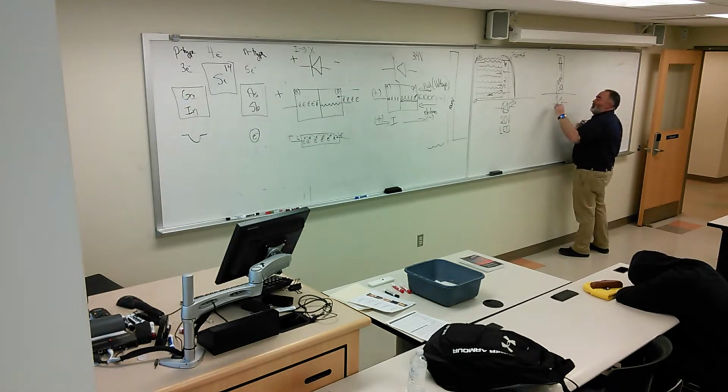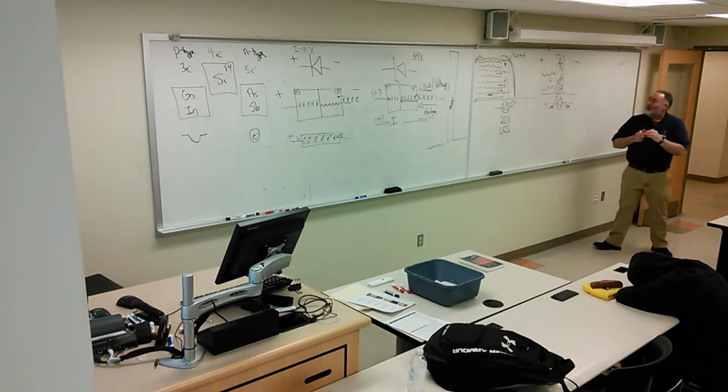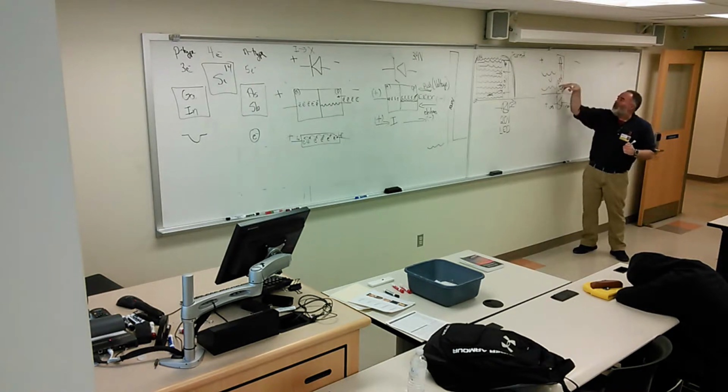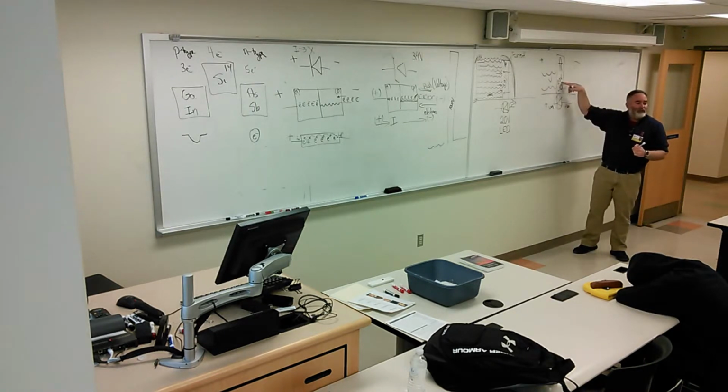This going backwards. This was the long lead of the LED that faces positive. This is the negative, the short lead of the LED that faces negative. Again, this is positive, this is negative. And here's the voltage. According to this, how much current flows if we're lower than 2 volts? Using the dam analogy.